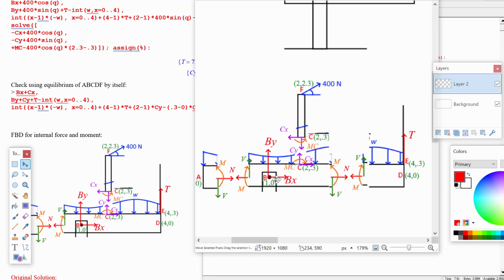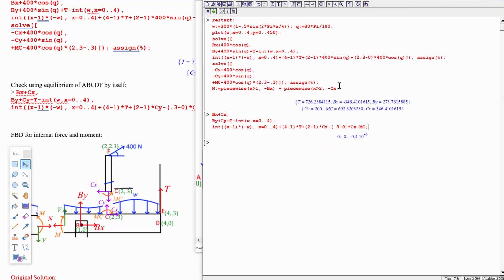So you can see as we pass bx and then cx, the normal force is going to have to reduce because we have more forces added to the right on this object. Now, in fact, bx is negative, so the normal force will actually increase by negative bx as we cross point B, but still we write down our piecewise function as a minus bx as you cross that point, and that'll take care of it. Okay, so that's the normal force.